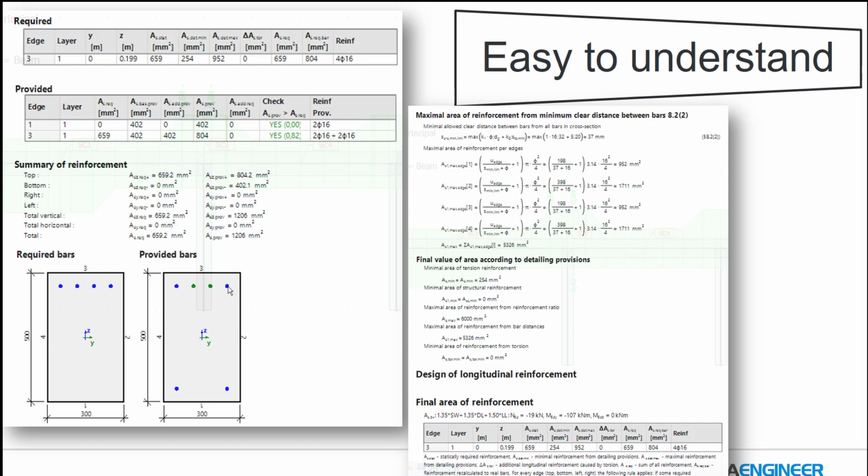So the blue color here, I'm repeating this point a little bit because it's very important, means you decided to add 4 bars inside the cross section, and you gave SCIA Engineer the option: if those 4 bars are not enough, then it can use extra 2 bars between them. And as long as the required reinforcement was 4 bars, then your 2 bars on the top side will not be enough, and SCIA will add extra 2 bars for you. But those 2 bars will not be on the full length of the member. It will be just where it is required.